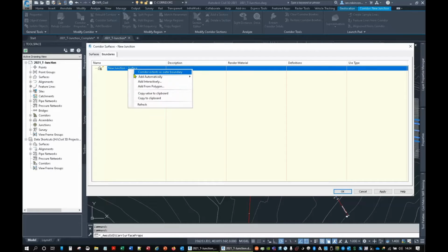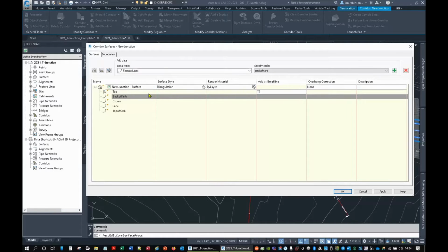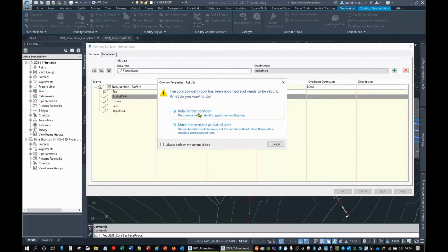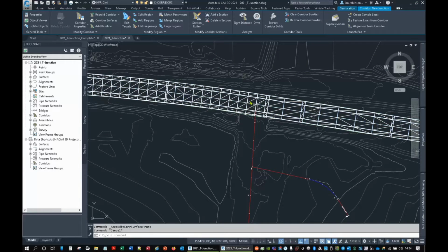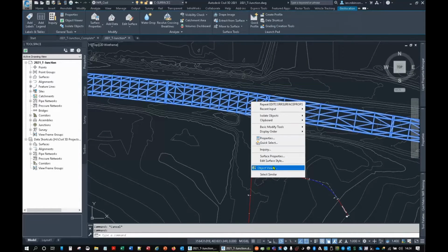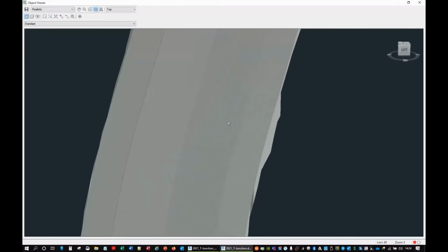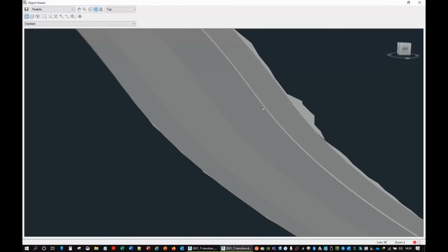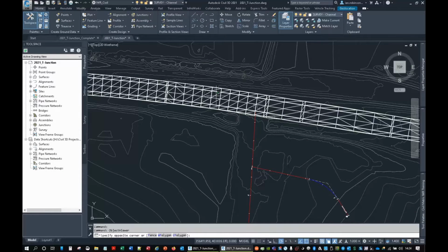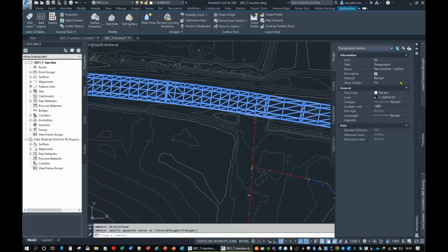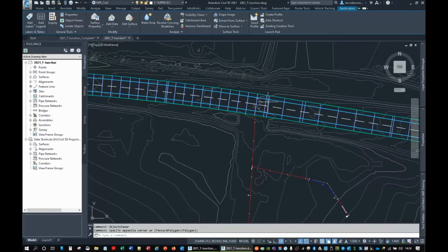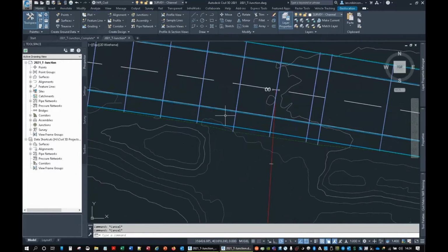And I'll put a boundary in as well. Corridor extents as a boundary because it goes around a corner, so we don't want it to triangulate across the edge. So what we should have here is some nice clean channel lines in a surface that we can set to target, which we have. So I'm going to target this point here and this point here where the junction is. So I don't need to see the surface. I was confident it was going to happen, but I wanted you to see it. We'll worry about removing the footpath and everything later on.